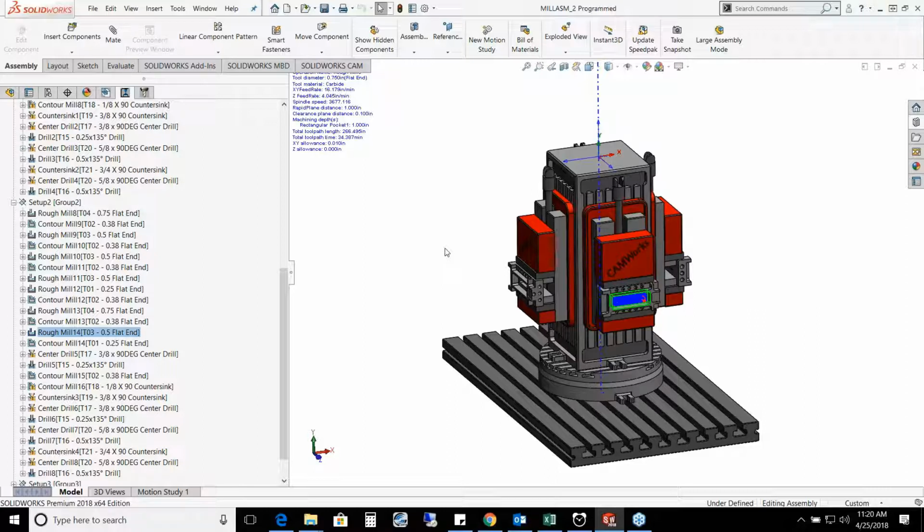So basically what we did is we did a quick, simple part in SOLIDWORKS CAM Standard, machined it, and programmed it. We didn't show the fixturing or anything of that nature, but we're still able to get a good quality tool path out to the floor quickly. We then went into the turning environment where we showed a 2-axis turn part, which is included in SOLIDWORKS CAM Pro. We then programmed a part in a vise in the assembly environment, which is also included in SOLIDWORKS CAM Pro. And then we also talked about the Volumill toolpath, multiple vise models, multiple models in the assembly mode with multi-plane indexing, which would be 4 and 5-axis indexing capabilities.